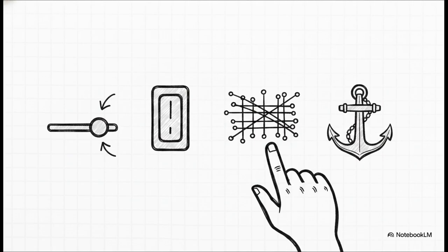If network limits matter to your load, better add optimal power flow, and if transmission losses matter, you have to explicitly include a loss-aware coordination condition, like a penalty factor. Do not add a feature unless you are answering a specific, declared need.